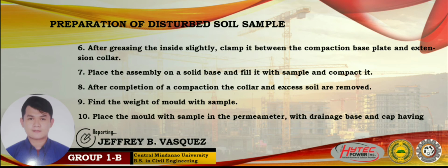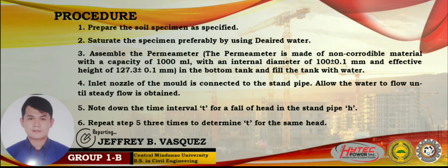Then find the weight of the mold with sample. Then place the mold with the sample in the permeameter. Here is the common procedure of both soil samples.